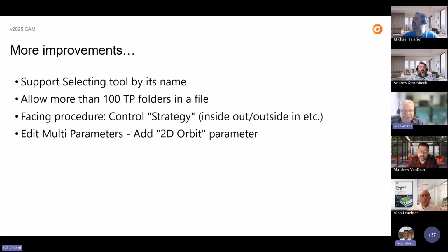First, Luca asks if there is a reconnection made in automatic safe mode with the part? Normally, yes. There is an option to make it not gouge check, but I would not suggest users to do it. It is automatically gouge checked.